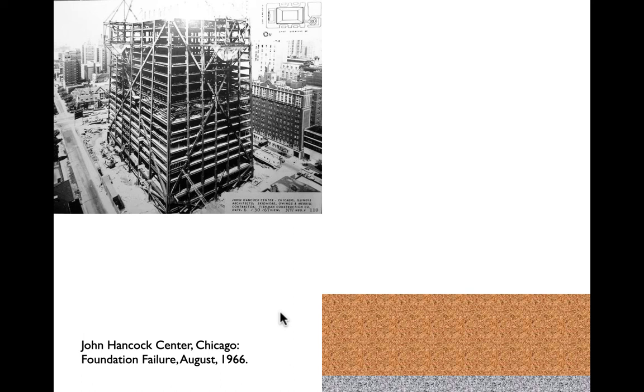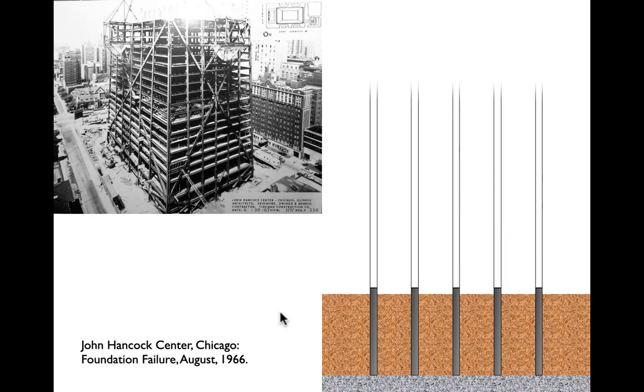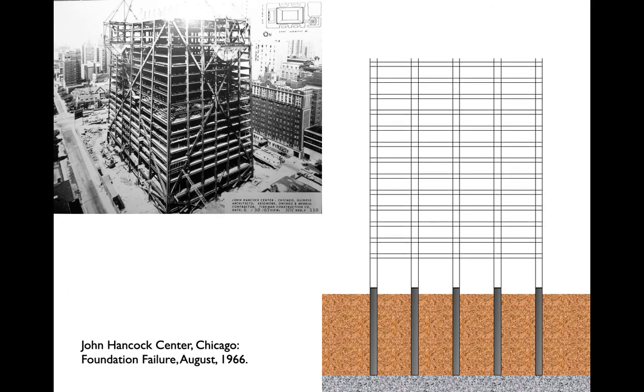The first thing that they do is they drill caissons. They send tubes down into the ground with drills inside of them. The drills remove the soil, and then the tube excludes the soil, prevents the caisson or the void from collapsing. They put rebar in, they throw concrete into it and let the concrete cure. Then they put the steel columns onto the caisson foundations and start to build the framing, right, as they go